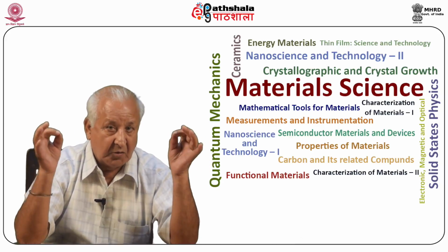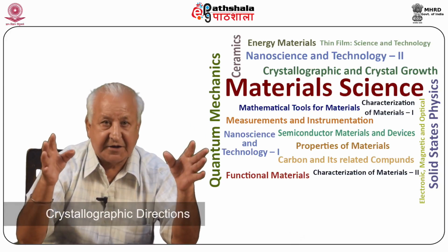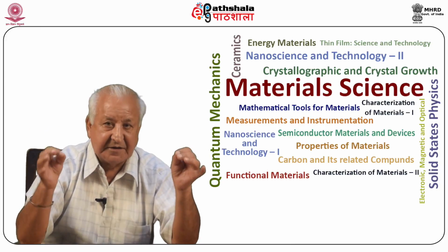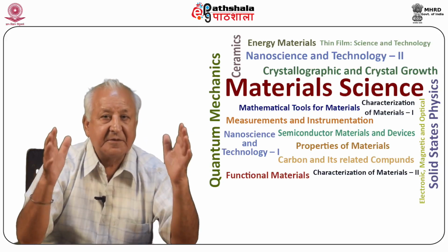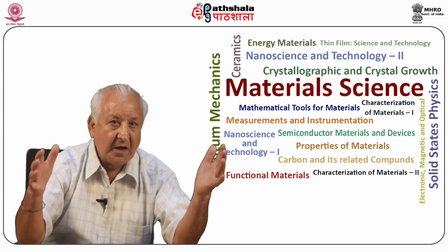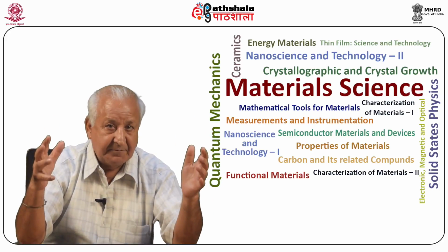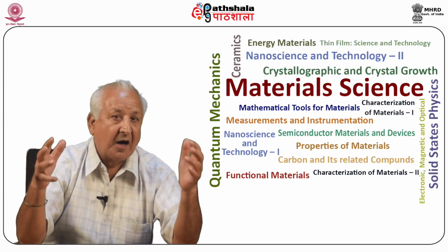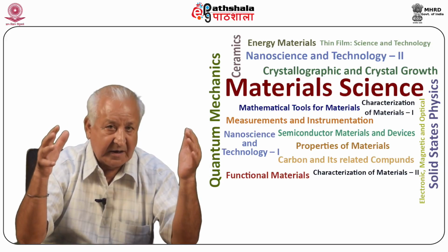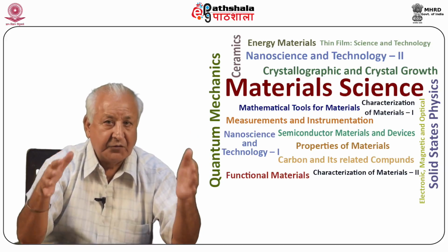In this method of growth, crystals usually grow most rapidly in certain crystallographic directions in which thermal conductivities are larger. It is on account of these reasons that growth from melt becomes primarily a problem of controlling temperatures and thermal gradients. There are several techniques by which this control can be achieved, and the prominent ones are Czochralski and other related techniques, the Bridgman-Stockbarger technique, growth by zone melting, and the Verneuil flame fusion technique.